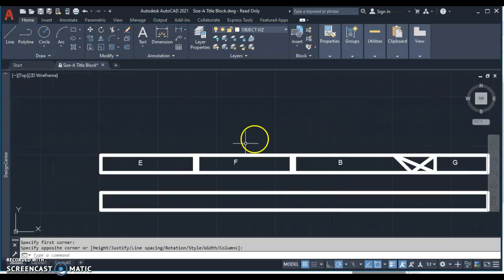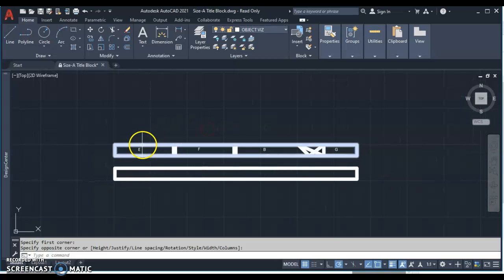So there's one part that's laid out, and it accounts for saw curves. I found that my reflective angles won't work together in this combination, but there is another combination that could make reflective angles work if you like to lay yours out that way. There are about 3 solutions to this problem, and there are different ways of laying it out. I want you to figure out the best solution and what works for you. I do have to plan to cut towards my waste when I'm doing this, and so there's some thinking that would go into play here as I actually cut this. This isn't the best option, but it is a working, functioning option.